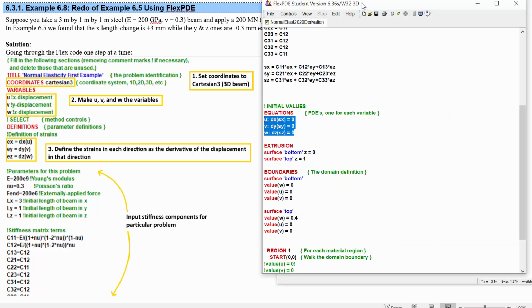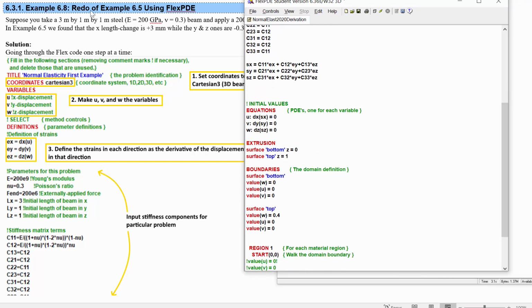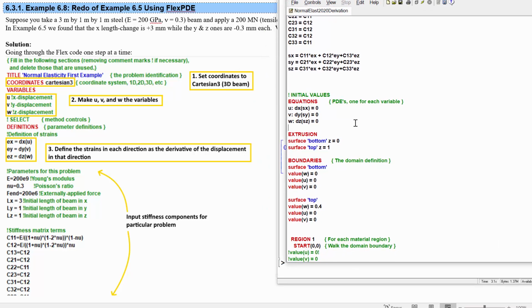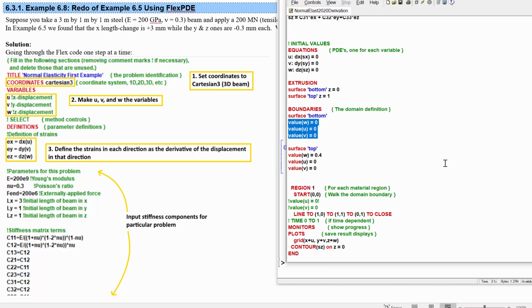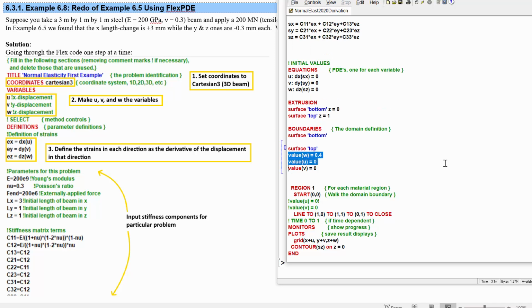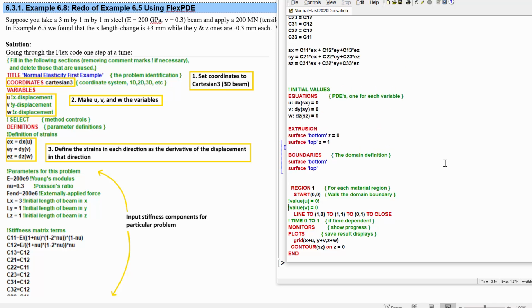Let's lay out the, we don't even have to set the right geometry yet. All we really need is that the stress is 200 meganewtons in the x direction, and there's no stresses in the other directions. So we can do that by getting rid of these boundary conditions on the top and bottom surface, and instead finding out which one is the x surface here and putting a boundary condition on that. We need it on the positive and negative x surfaces. So let's see. Here what we do is we change x. We have y equal to 0, and then we walk to 1, 0.